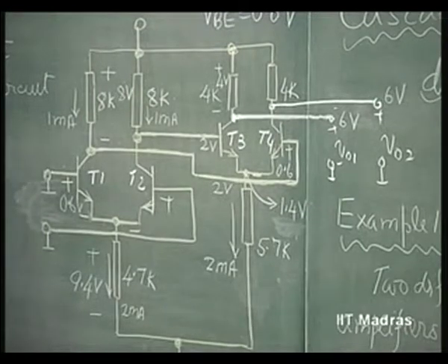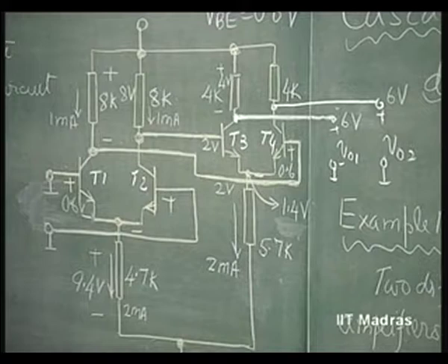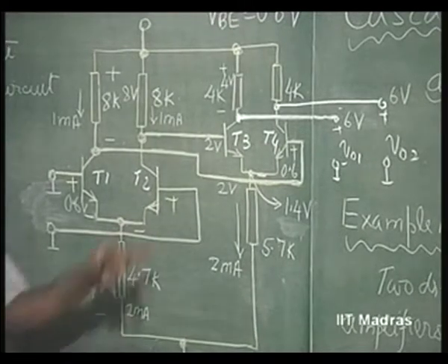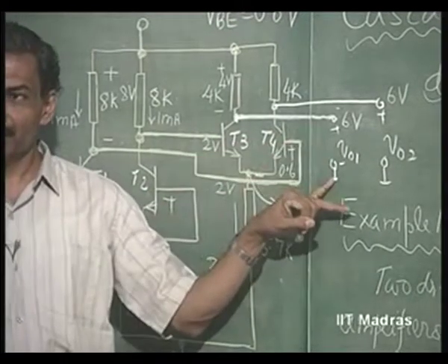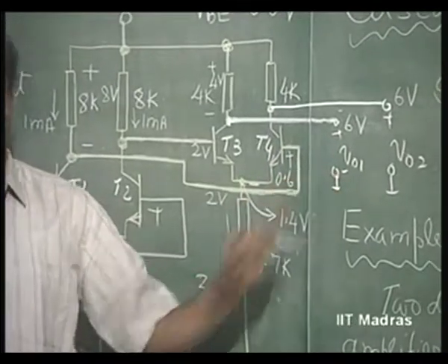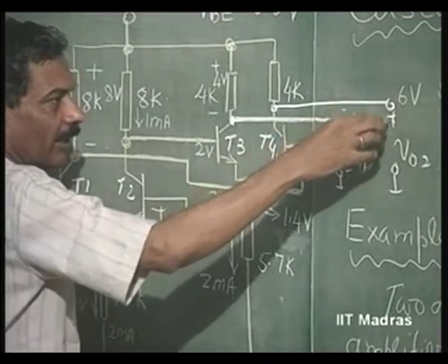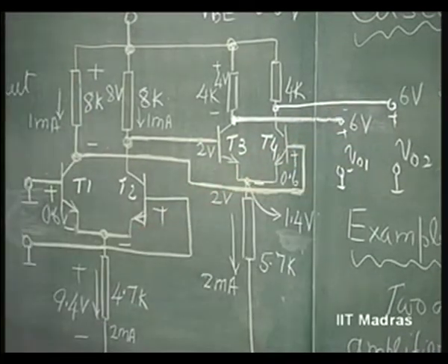So, you can consider that if it is single ended output, the quiescent voltage of this amplifier is 6 volts, or you can consider the offset as really 6 volts, right. It is not really offset because we have purposely fixed it at 6 volts. We could have made it equal to 0 volts if we wanted, right.